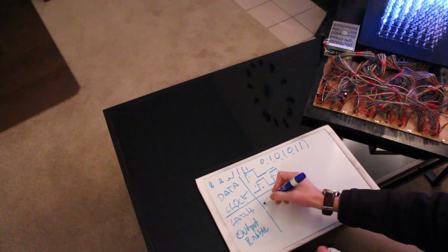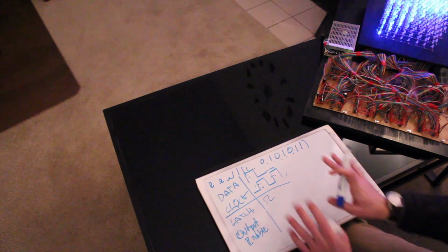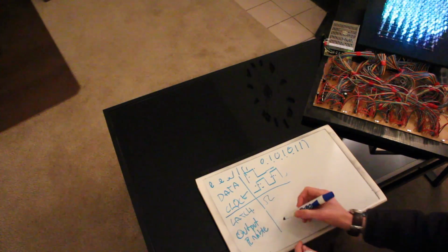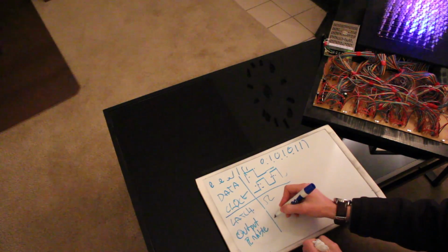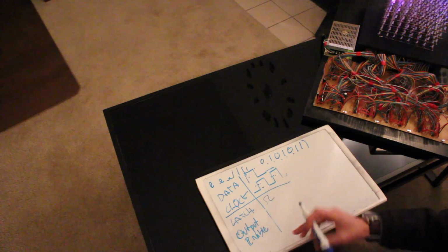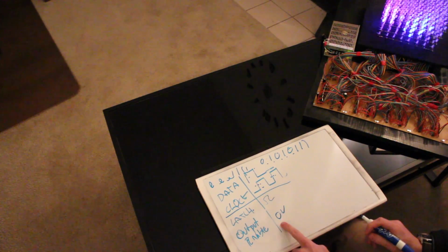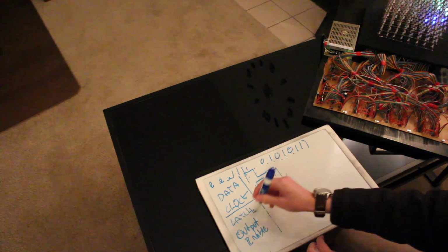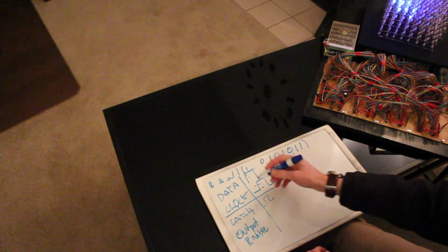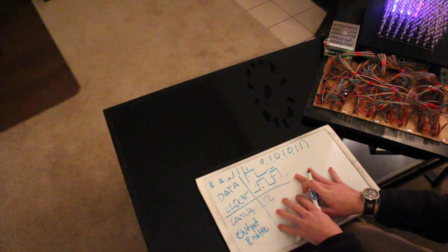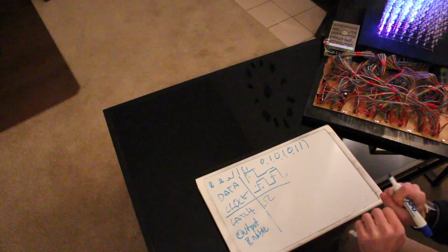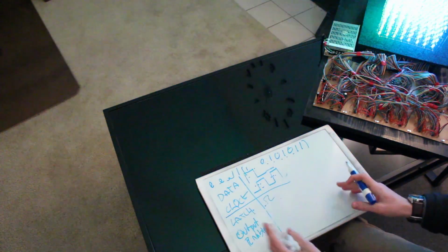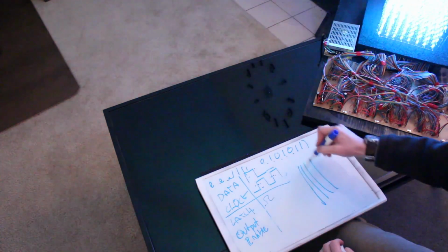As soon as you latch it, as soon as this latch pin just goes high for a second, this data becomes the outputs of the shift registers. The output enable, if you don't have to do anything with it, you could just keep this low, so you keep that at 0 volts. But what I decided to do was toggle this pin as I'm latching the new data in, because you've had a value at the output before this, and now suddenly you changed it quickly. Well, it's going to take time for the LEDs to turn off and on, and you're controlling both sides of that grid. Remember that grid I was just showing you?